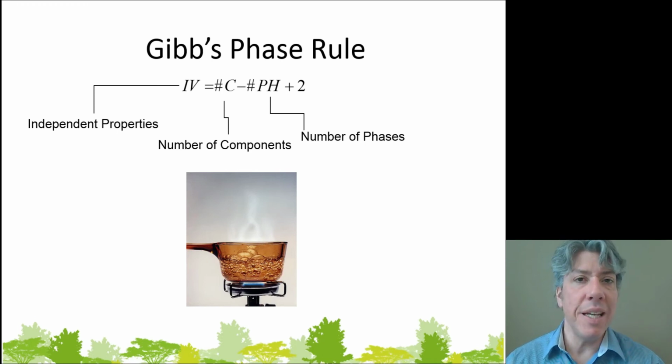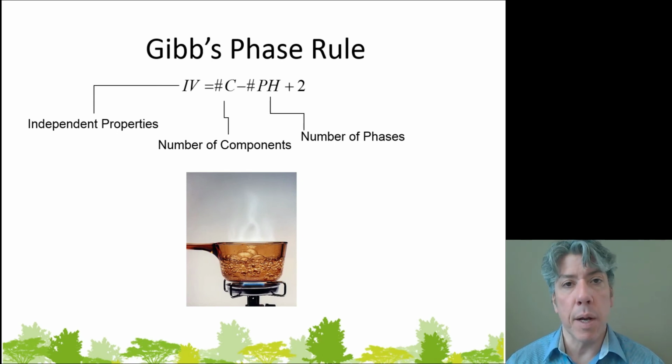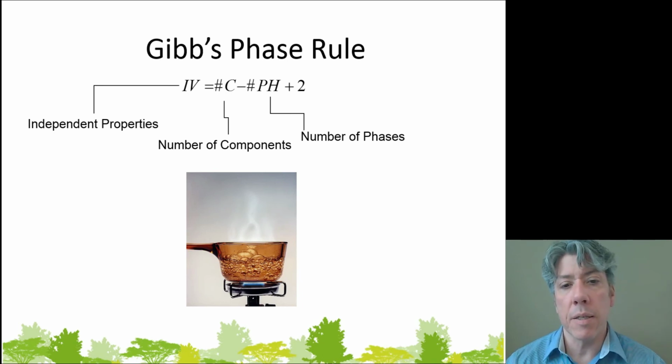But as you decrease the pressure, water will boil at a lower temperature. And so you've naturally already specified a property, and that is pressure. That's an intensive property. And then when two phases are present, in other words, when there's gas and liquid, everything else is fixed. The specific volume, the temperature of boiling, and all these things are fixed and unchanging.